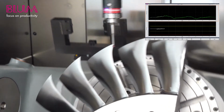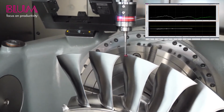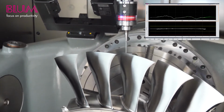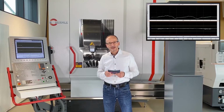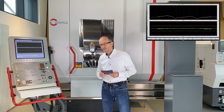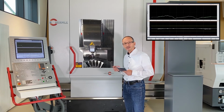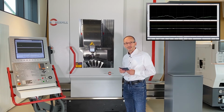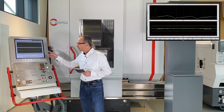By using a DIGILOG probe, the component is no longer measured point by point. Instead, we scan the individual turbine blades. As a result, we receive a holistic overview of the entire turbine blade profile. One blade after the other is scanned. It takes less than 30 minutes to measure the component fully. In this case, our software is integrated directly into the machine control. The data is visualized directly on the control screen.